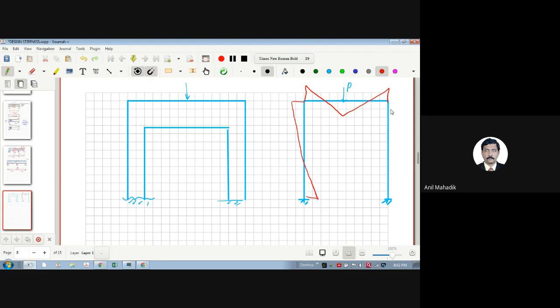Okay. Now you can see here the bending moment is max here, M_s max. Sagging moment यहाँ hogging moment है. So these are the maximum values. So यहाँ support पे hogging moment है, center पे sagging moment. So at the center there is a crack here. Then here also you'll find the crack somewhere here at the support. Oh, उल्टा निकाला.